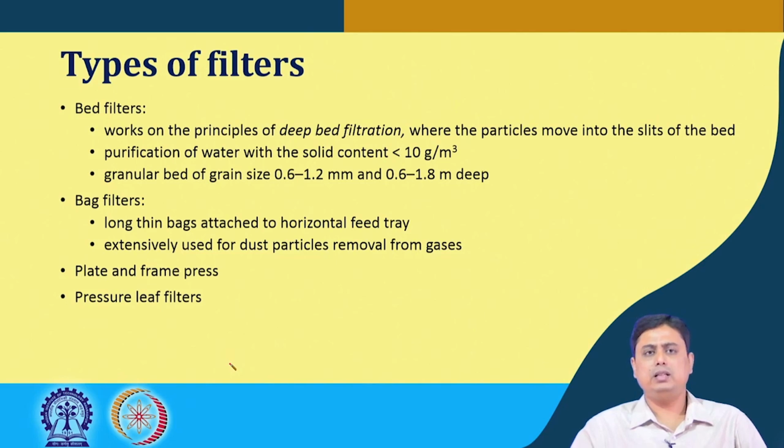Typically these bag filters consist of long thin bags attached to a horizontal feed tray. In such cases the surface area that is available is lower and the filtration is very low. So, for high throughput operation, such filters are now obsolete, but when it comes to the dust particle removal from gases, these are still in use.